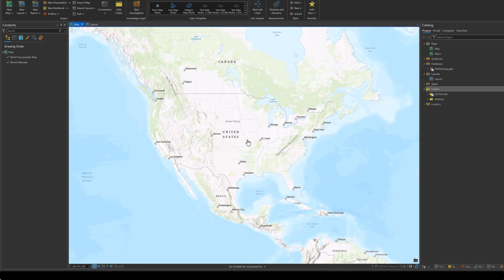But that has little to no value when you start trying to do some actual geospatial analysis. And it can cause problems when you try to use your data in other products such as Autodesk or Bentley that have a coordinate system set. It may come in the wrong spot, for instance.